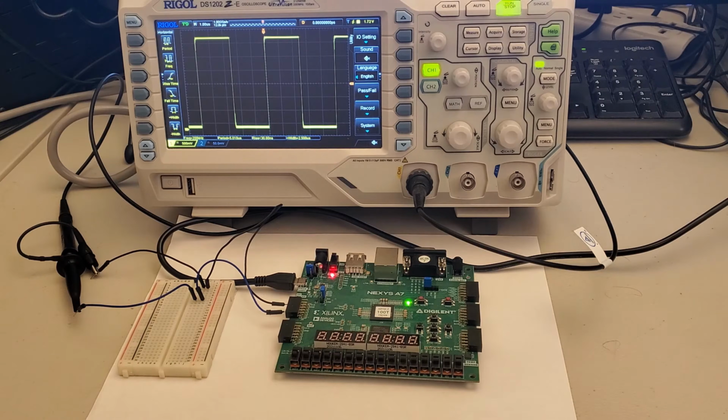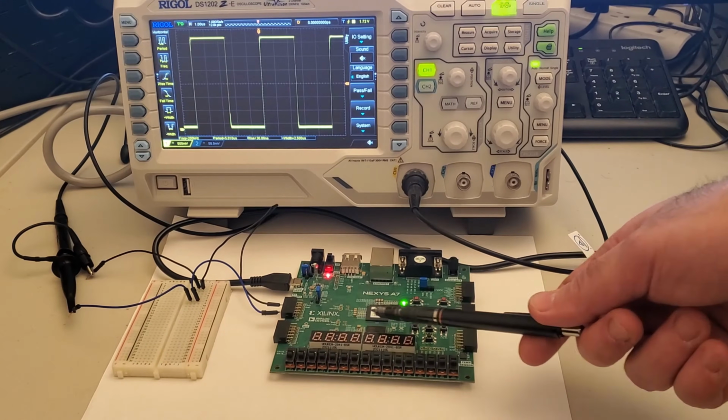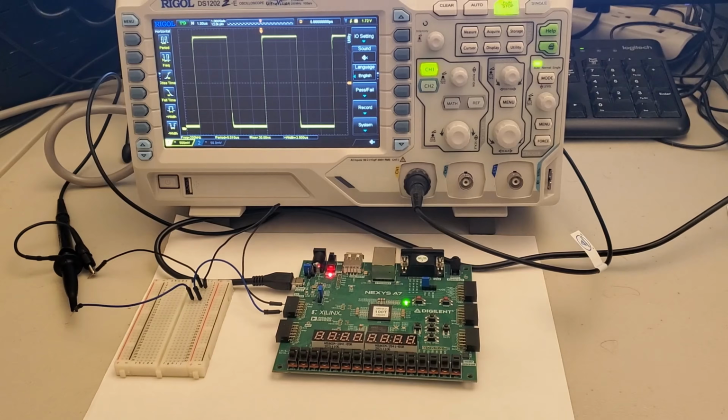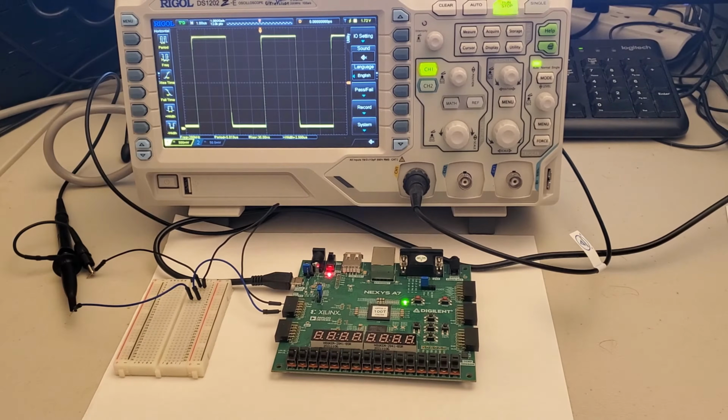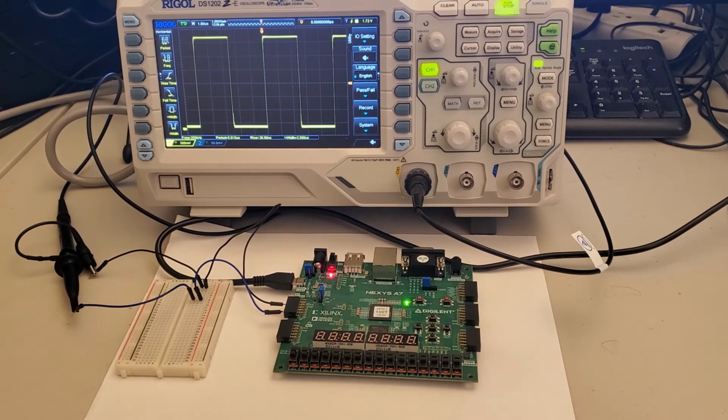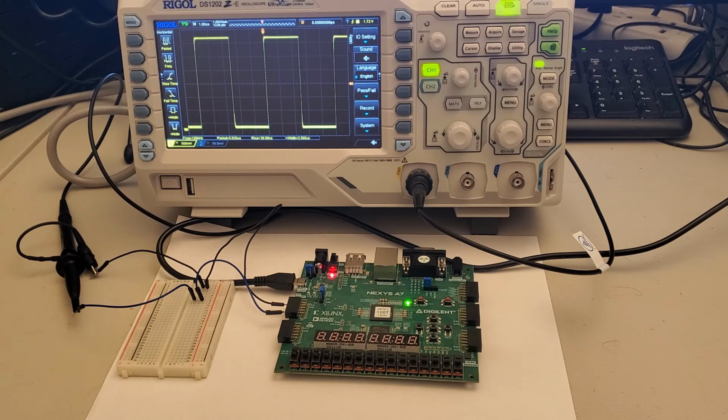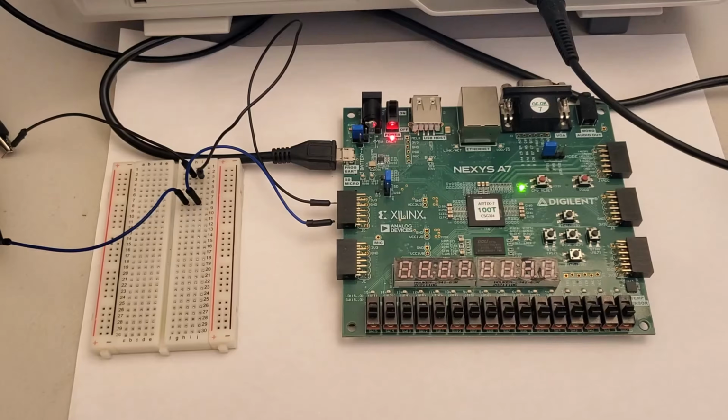In this tutorial, we are using Nexys A7-100T FPGA. This is a very popular FPGA that is often used in electrical and computer engineering programs in the US and Europe. However, everything explained in this tutorial can easily be used in the case of other FPGAs. The Verilog code will be the same, the only difference will be in the constraint file and how the clock is attached to the actual ports of the Verilog module.